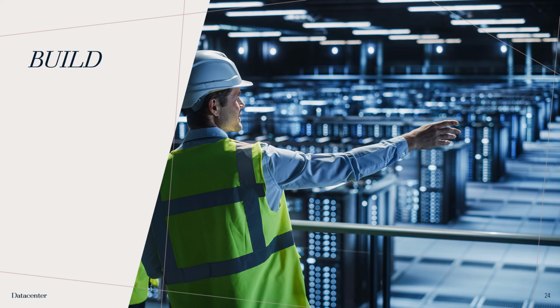Another essential part of a data center is its cooling. A de facto standard is a double flooring and a system of cold and hot aisles. The cold aisle should be roofed over to prevent the mixing of hot and cold air. The server racks need to be placed in a specific way. They should inhale the cold air from their front aisle and exhale it hot out their back. The double flooring allows the cold air to be led to the correct place and also hides the metallic cables. Optical fibers should preferably be led up over the rack in a special plastic trough.